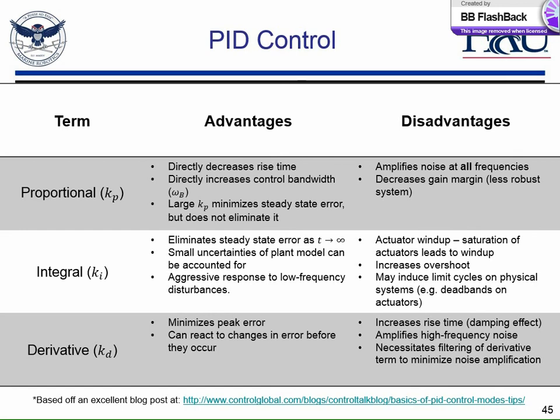What that means is if you're starting to grow up like this, and your PID controller wants you to keep on going up like this, but at a certain point your motor's saturated, so you're only able to go up by that rate. And now you have this giant area that you're integrating, much longer than your integral control actually wants you to integrate it. And that drives your system into an oscillation, right? So that can be quite bad for a system, so you have to deal with it through an anti-windup controller, right? Where either you'll eliminate the integral term as soon as you get within a margin of your steady state response, or you only enact your integral term within a margin of the steady state response.